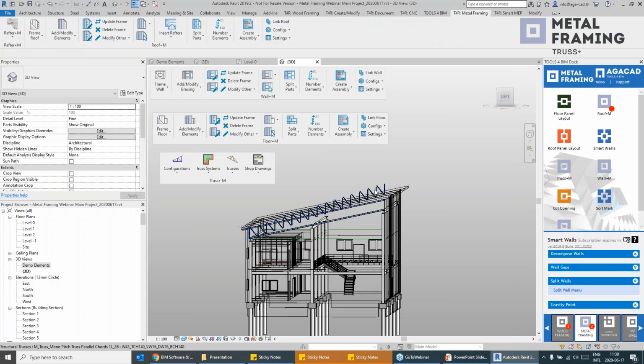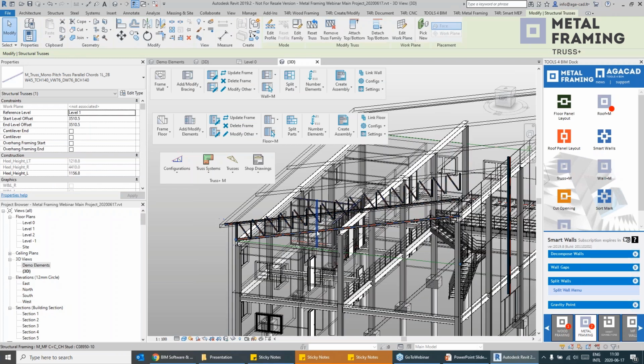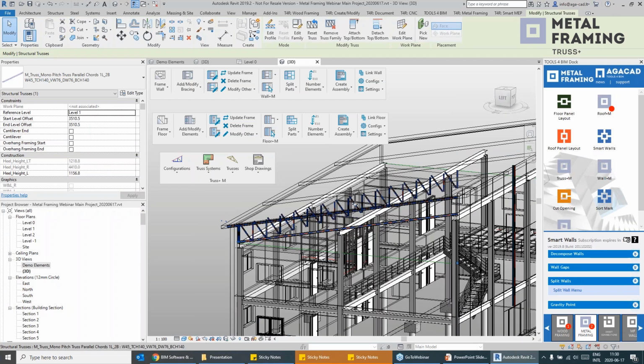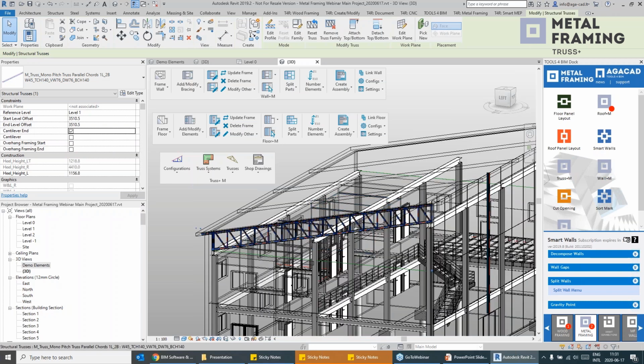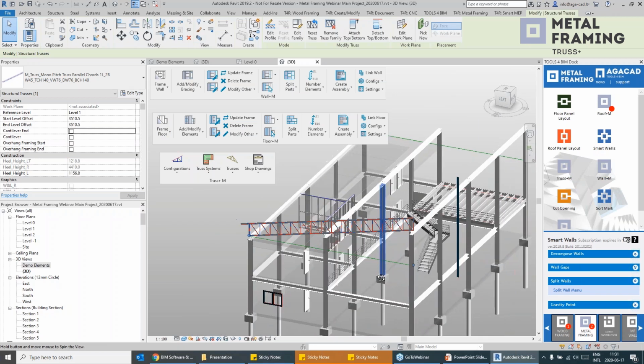However, there's a small glitch with Revit. It has nothing to do with our software, but sometimes it freezes with the parameters. So what you sometimes need to do is change something in Revit, and as you can see, Revit then refreshes the family and starts to work, because arrays in a family are sometimes not updated efficiently. So sometimes you just need to change something and change it back, and the truss seems fine.